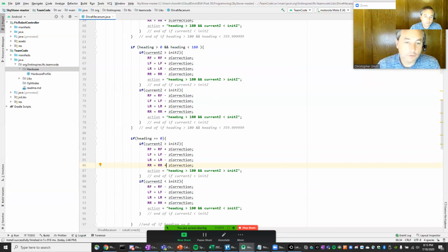But one of the things that makes this complicated is that normally that's the way it would be, but because I'm using a negative value on the gyro sensor, everything is actually inverted. So this is going to be negative, this will be positive, this will be positive, and this will be negative. And then we'll just reverse that for the next one: negative, negative, and positive. Yep.